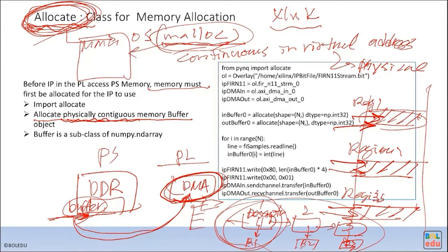And 3 transfers take a lot of overhead. When the data transfers, it has to let the driver know, okay, I transferred the first region. Then the driver programs the second region, and it starts transferring the second. When the second is done, it starts transferring the third one. So it has a lot of synchronization overhead. It will be very, very slow. You will find that transferring data is fast, but the synchronization takes up a lot of time.